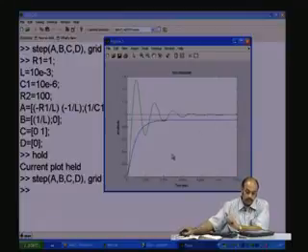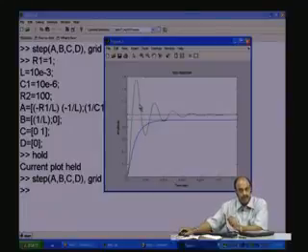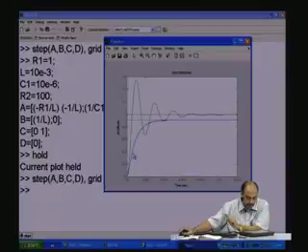0. It rises quickly, but shoots beyond the value 1, and then you have damped frequency of oscillation as shown here. Now, what is causing this? From the time domain, it may not be so very evident. Probably we may have to look at the frequency domain and the pole-zero domain. The pole-zero domain will give a very interesting result.